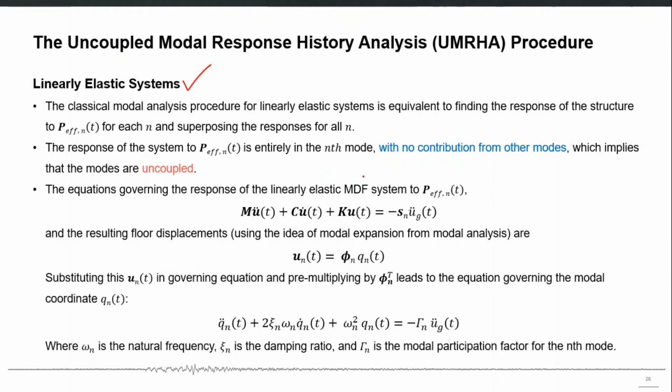So the classical modal analysis procedure for linear elastic system is equivalent to finding the response of the structure to the effective earthquake forces of each mode separately, and then combining or superposing the response for all vibration modes. So in the classical modal analysis, we calculate the response for each mode against the effective earthquake forces of those modes, and then sum those responses in the time domain directly to get the dynamic response of multiple degree of